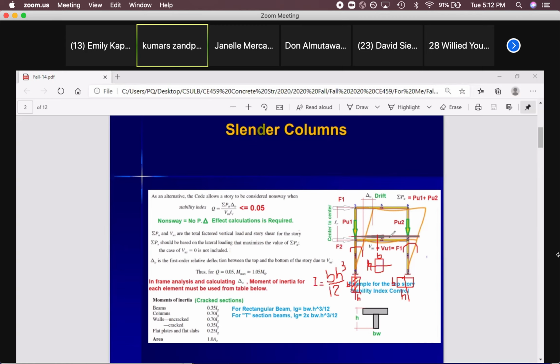But if you have a slab and a rectangular beam that they pour together, and there is rebar involved between these two, in this case you can consider 75% IG for this beam. Again, rectangular section, don't go after the T section. Just consider that as rectangular, but double of that as your I crack.